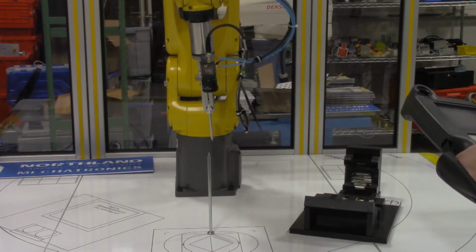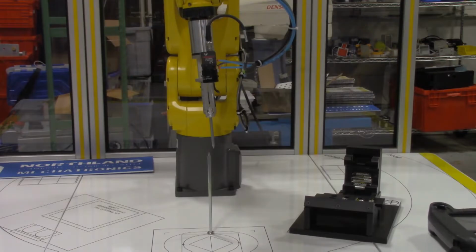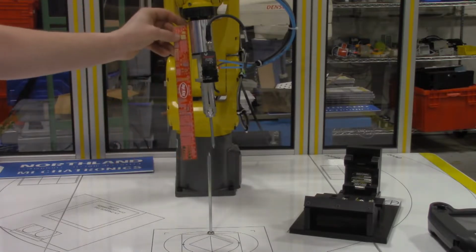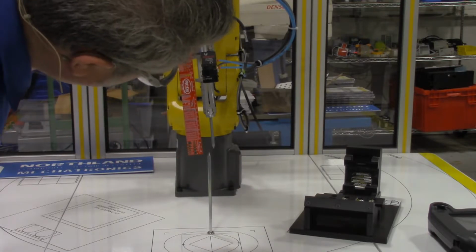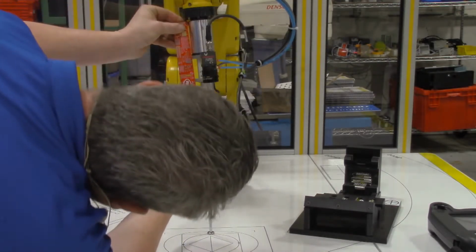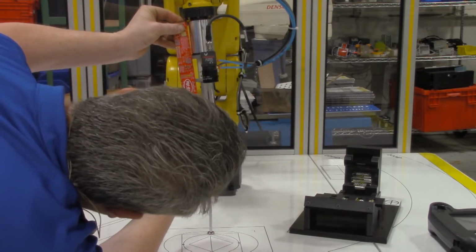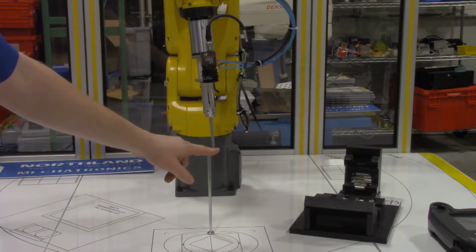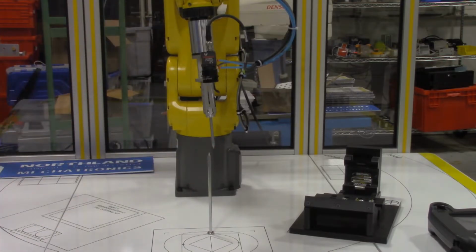All right. So that's interesting for us to note. So let's go ahead and change our tooling so we get it set up for our long tool as we were planning to do. And to do that, we're going to need to take some measurements. In this case, I've got a ruler that measures in millimeters. And if I go to the end of that tooling here, way down, it looks like I'm getting about 30 centimeters from this end of tool to the tip right here. So that would be the Z offset length in this case.